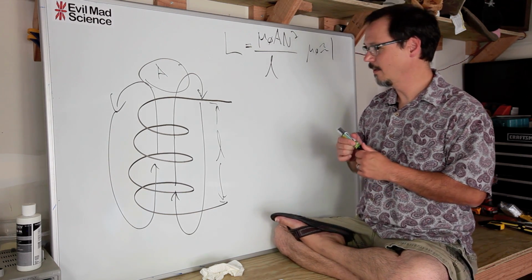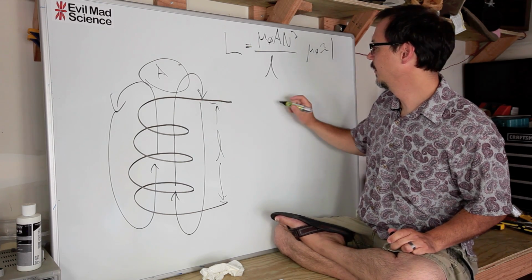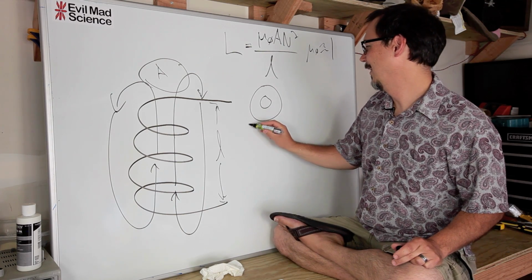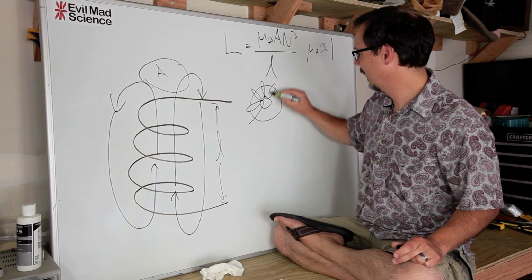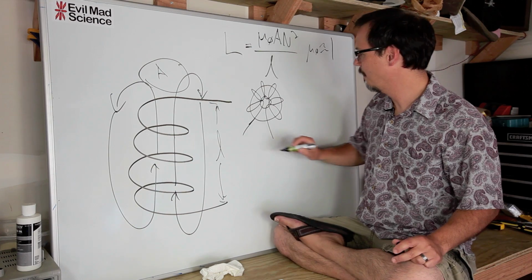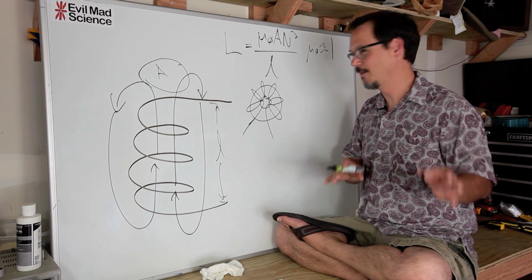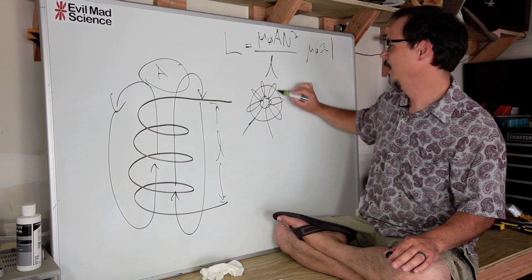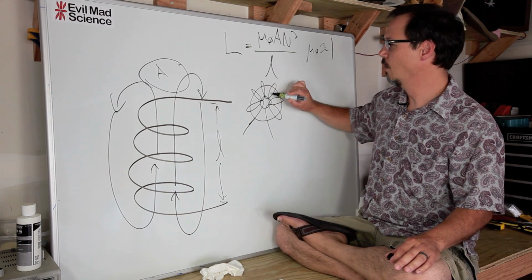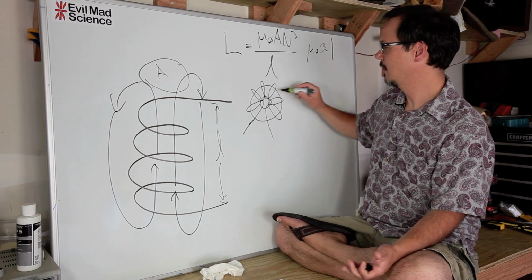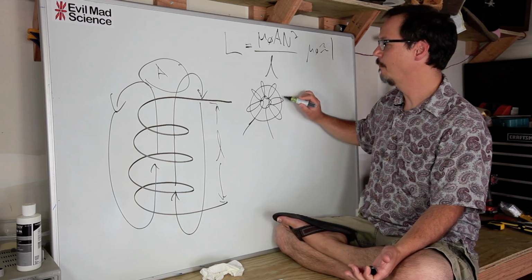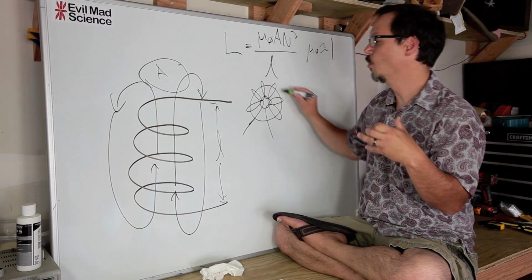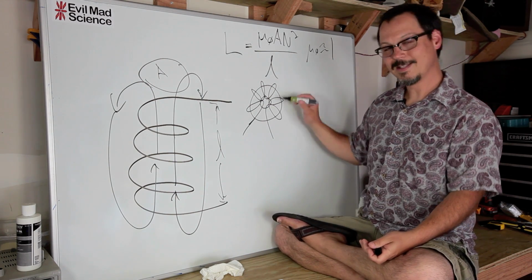There are a couple of different techniques. One thing that they do is they will put it on a toroid. This isn't the best thing to do, but they'll wind an inductor like this. All the RF guys know this because they make chokes. I'll talk about a choke in a minute. But this maintains the majority of the magnetic flux within the core material because the permeability of this material is a lot better than the permeability of air. And so the flux will tend to stay inside the more permeable material. But it's not a perfect solution.